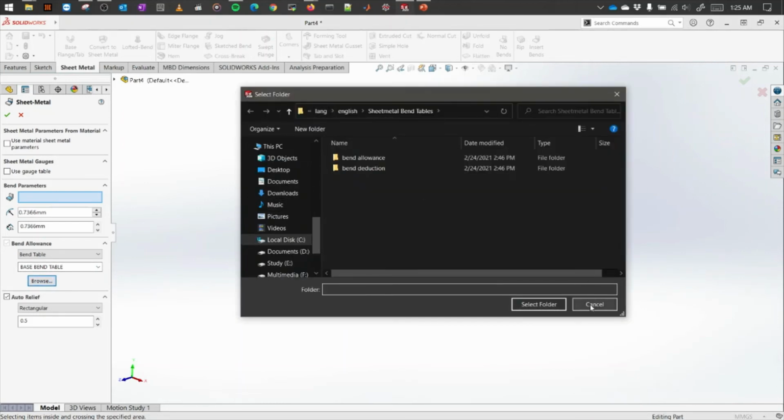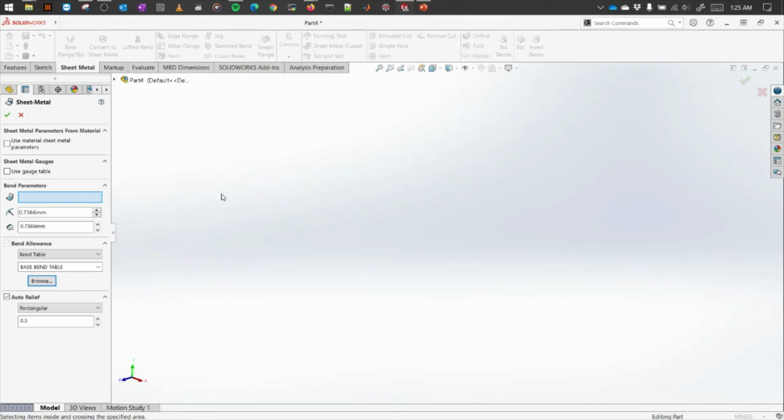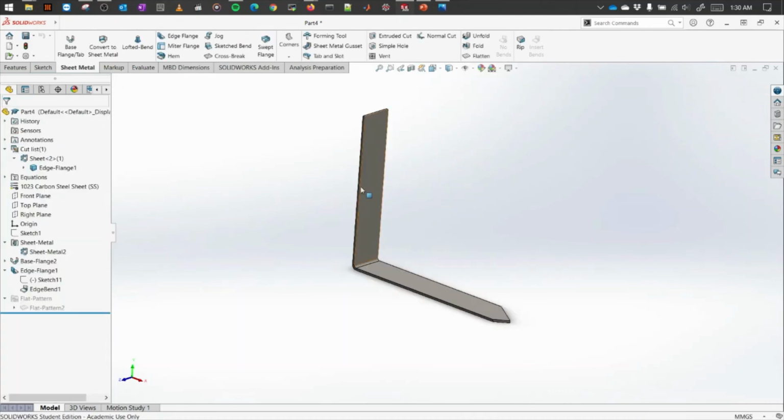I haven't created one for this workshop, but I can certainly create one and send it to you if you require. Once you've selected all the parameters and made the changes you wanted, let's get back to the K factor first. You just click OK, and all the changes you have made will be applied to the material you have here.